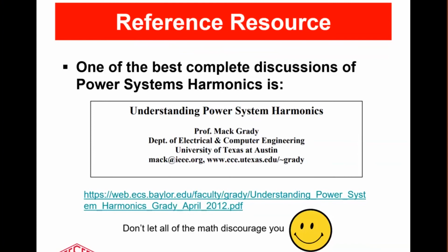Good morning, Bill and Andrea. This is Brian Cole from Ameren, Illinois. I'm curious, you gave a demo with the two units, and in our test lab, we have the TESCO MQB boards, the new version. I'm curious, can we simulate some of the harmonic conditions in those MQBs? Yes, you can. You can generate any harmonic that you can write down the coefficients for.